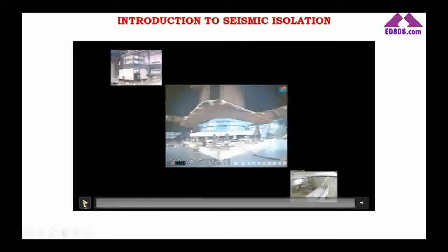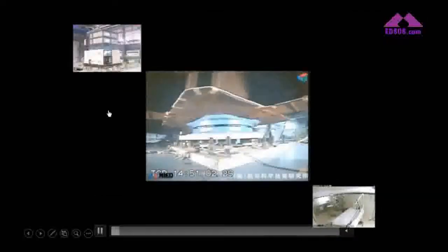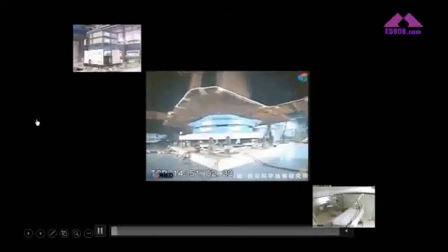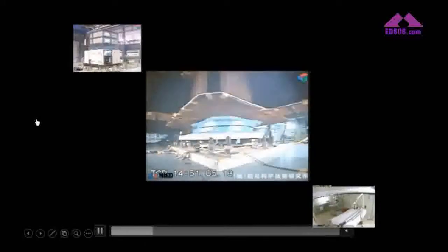And this is a very similar shake table test footage for a friction isolator, again a hospital. You see the building moves. Again, the unfixed elements move in the building, and the isolator moves nearly 67 centimeters. I repeat it again. Check now. It starts to move slowly. Then right now it is nearly 70 centimeters maximum displacement.